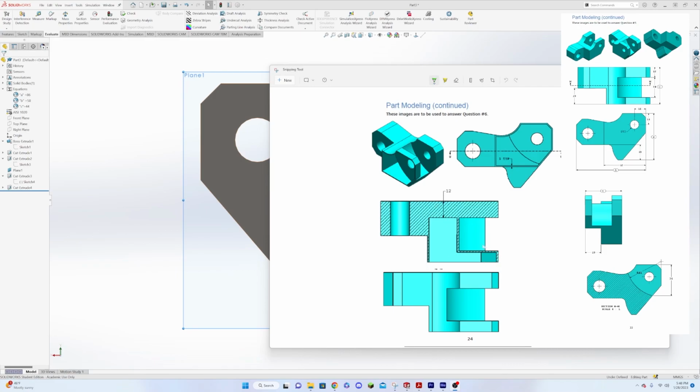So we've got these two cutouts here, and you can see once again that this deeper one is referenced off the back plane, not off the front. So when we make these cutouts, we want to make it off the back plane. And then you can also see that we have a typical call out for our width here. So our width is going to be 1 millimeter. And basically if they give that typical call out, then everywhere where we have that shell, we're going to make that shell 1 millimeter. And even though this isn't necessarily called out on this face, we're going to make the assumption that this is 1 millimeter here in this cutout. So let's get started with that. I'll add this to the screen and we'll get going.